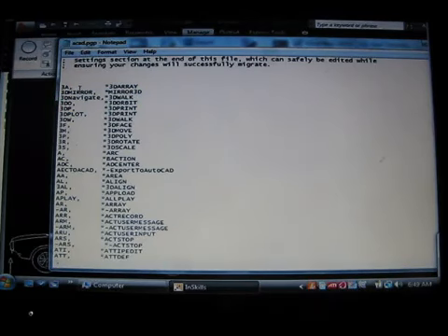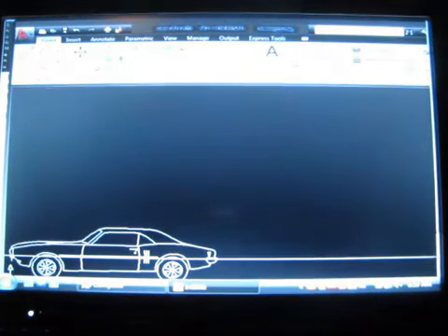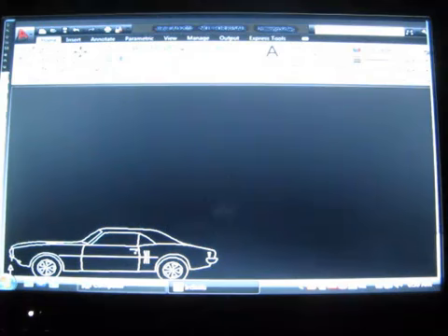As you can see, 3A will do your three. Out of the box, AutoCAD 2010 comes with 3 workspaces. Each one is different from the other and each one fills certain needs. The AutoCAD Classic workspace will set the interface to the way AutoCAD used to be in a few releases ago. It has toolbars and the menu bar, and the ribbon is turned off.